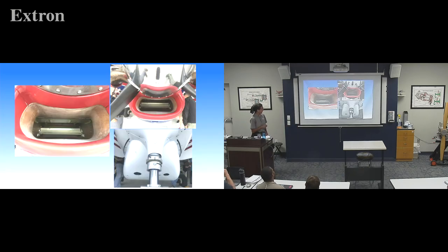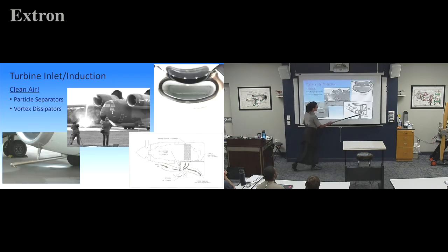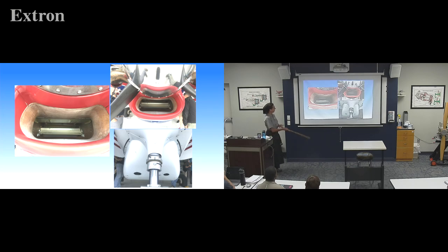These are pictures I took when the Kodiak was here, and you can look up in there and see the ice vane. Cool thing: on the King Air, it just dumps out the bottom. But on the Kodiak, because that goes back inside the fuselage, our belly pod needs special ducting to allow all that dirt to drop out the bottom. So if you see those little pipes coming out the belly pod, that's what it's for.